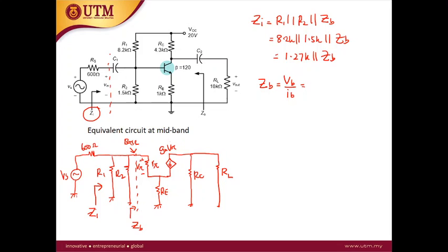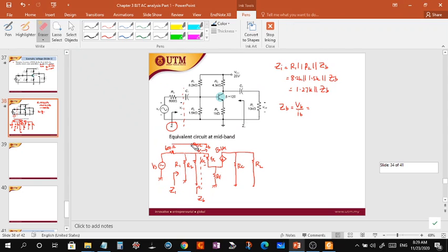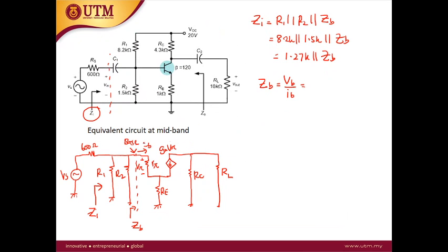Okay, the base current is here. This is the base current. Sorry, this is the base current. Okay, how about the VB? VB is the sum of the voltage drop at the R pi and the voltage drop at the RE. For the voltage drop at the R pi, we can use the V pi, but now we want to express it using the IB. So we use IB times R pi. R pi here, we have calculated, is 1.32k. Okay, and then plus the voltage drop at RE. RE is 1k. This is IB, and this is IE.